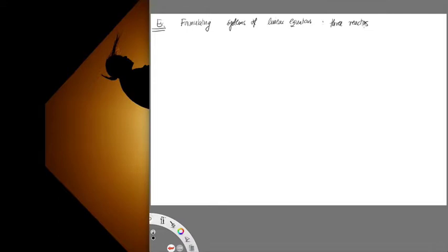So obviously, since we are flowing oil and gas around, we need to know a thing or two of how that works. And as an engineer, again, you want to calculate what the flux is. That will also tell you the velocity. Velocity determines the type of flow you have. And you will get to that in transport, but essentially you would like to have a laminar regime. If you're switching from laminar to turbulent, it's that fast that it's getting turbulent, that is much harder to control.